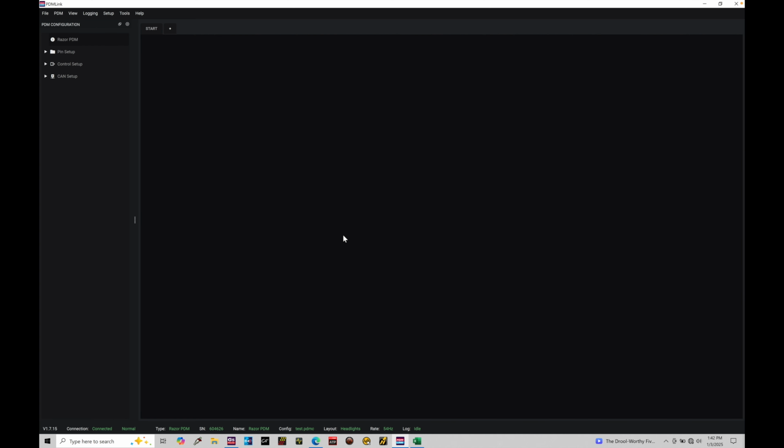You can actually test your real-time current draw, whether it's inrush or continuous, using your PDM software when you're controlling the device, doing a test function. I'm going to demonstrate that here, looking at turning on some LED lights, just so you can see what that looks like here on screen and starting to communicate with the PDM module, just a basic test. But you'll be able to use that to populate an Excel spreadsheet to figure out and calculate what the maximum possible continuous amperage draw is going to be on all your devices, as well as the possible inrush amperage that you have on your devices.